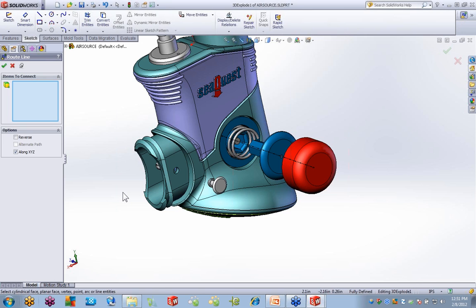So these are some of the things that have intrigued me about multiple bodies. We can now blur that line between a multibody part and its solids. It's integrated throughout the software in a lot of different commands. We can create folders. We can make it show up in the bill of materials. We can get mass properties. We can insert them into their own parts and save them as bodies separately. So there's quite a bit there when it relates to multibodies.